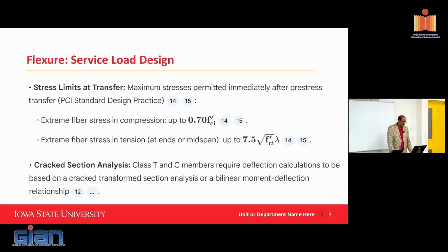Again, this is something I touched on briefly yesterday, so I put in some of these things to re-emphasize. For prestressed concrete, you have not just service and ultimate, but you also have to look at stress limits at transfer. When you release the prestressing force, especially with the pre-tension operation, the concrete is pretty young. It hasn't matured, it hasn't gained full strength. So you could potentially crack.